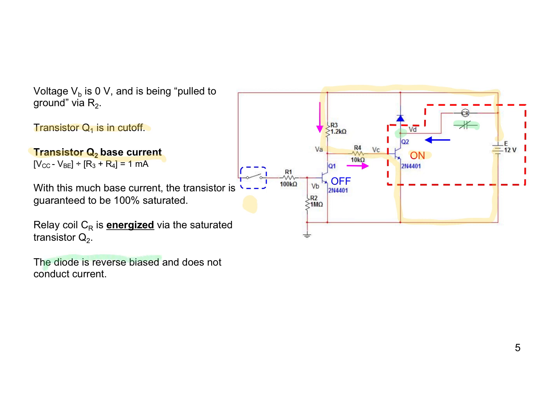The diode here, notice the polarity right there is the cathode. This is the positive point. It is reverse biased, and we'll see shortly why that diode is there. But right now it's reverse biased. It's not conducting current.